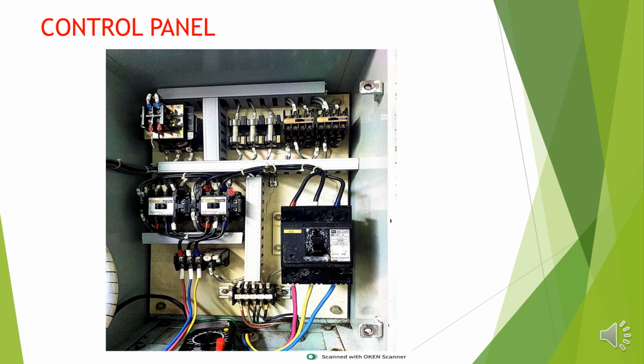And in the control circuit, we know first the primary side of the transformer, the primary winding of the transformer, there are 440 volt. Here you can see, you can measure the supply 440 volt, and in between that one fuse is connected, that is F1. You can check the continuity if the fuse is faulty, or if you find that here the 440 volt power is not there, you can check this fuse also.